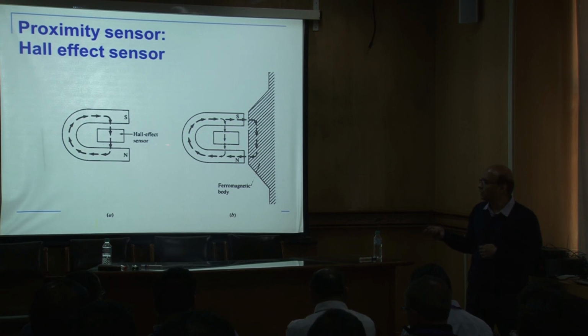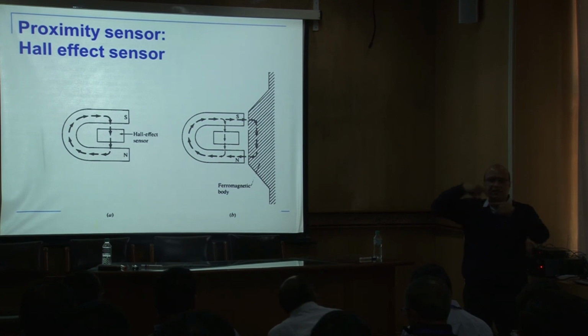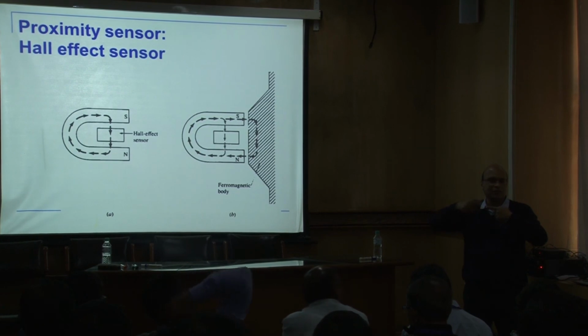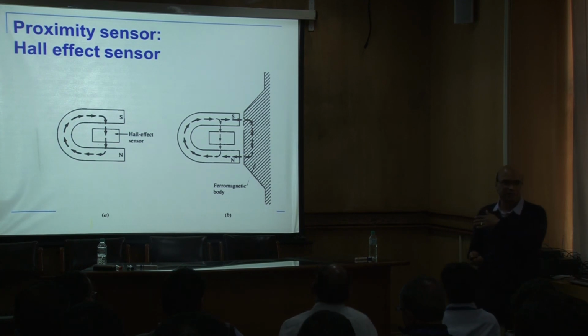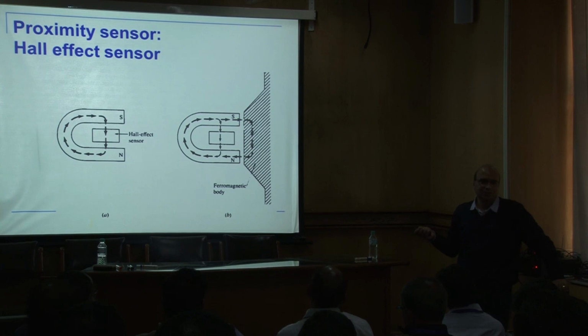So at the output of the engine, on the shaft, there is a small projection, something like this, and depending on when it is rotating, how many times that projection is coming. From that it knows how many times it has gone round. So there is the counter. There is engine RPM. Now the wheel RPM is after the gearbox, right? So this sensor is also used for measuring the car speed. So in robotics we can use it for measuring distance, proximity, but it is also used extensively in other applications.